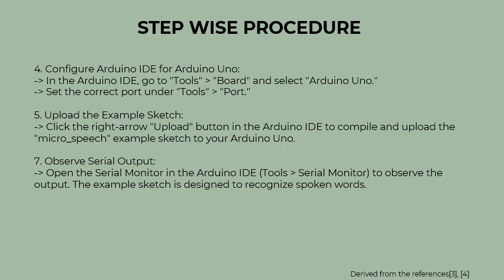Next, upload the example sketch onto the Arduino board. Click on the right arrow upload button in Arduino IDE to compile and upload the microspeech example in the Arduino. Now, we can see the output in the serial monitor.